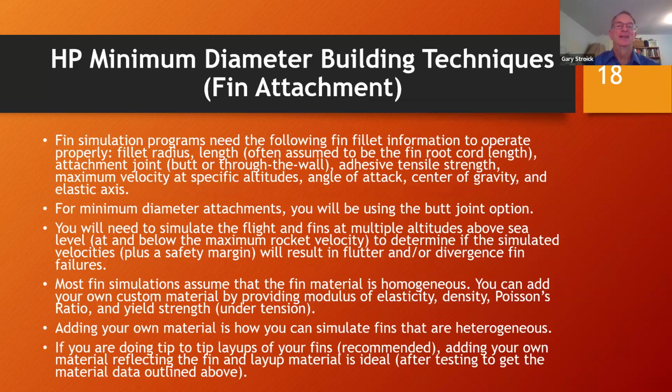All right, so these fin simulation programs will typically want to know specific information. They're going to want to know, well, what's the radius of my fin fillet? What's the length of the fin fillet? Usually it's the length of the root chord of the fin, which is on the airframe. They're going to want to know, well, what type of joint are you using?